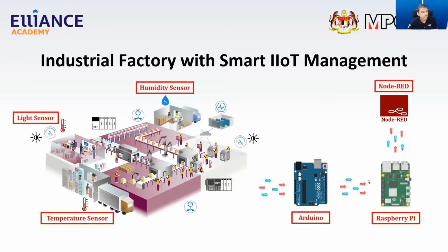Okay, so for example here, we can take temperature sensor, light sensor, and humidity sensor. These are the main three we listed out here. There are actually more we can use on production floors. So temperature sensor, why do we need a temperature sensor in the building? For example, when we are using some kind of chemicals in production, the motor, the servo, the machine, if it's running too long and the temperature in the surroundings increases, it might damage some products. So we can use these sensors to monitor the temperature in the surroundings, and it will alert us